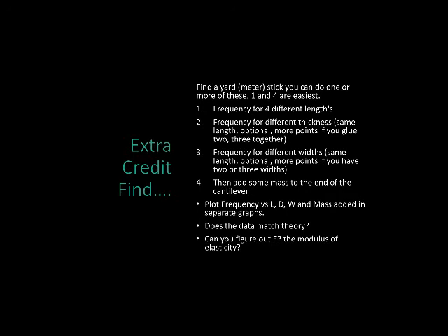Okay, and see if you can figure out what the elastic modulus is by looking at the frequency at 2 different lengths or 3 different lengths. And you can back calculate out what the elastic modulus should be from a couple of experiments. So this will be an extra credit for you if you want to do it, or just videotape it and analyze it a little bit.